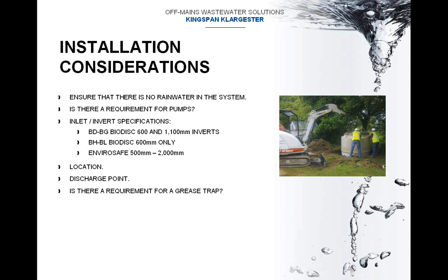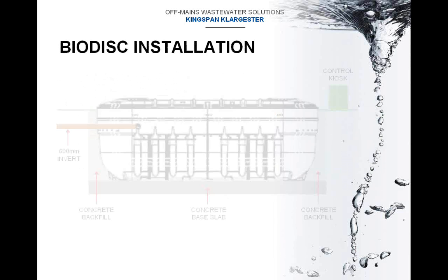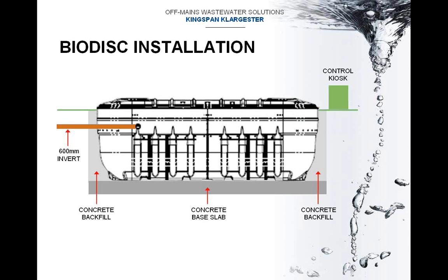Location is critical. Can the plant be easily desludged or maintained? Where is the discharge point? Is there a requirement for a grease trap? This slide shows a typical installation of a BIODISC. Note the invert at 600 mm, concrete slab and concrete backfill.